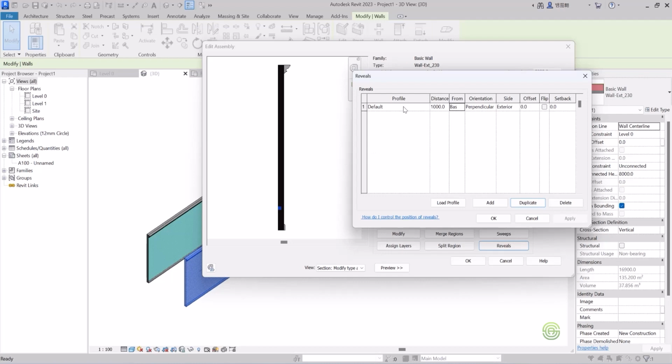It is scooping out the wall. Now in default, just change this to family 3 and now click apply. Now we can see we have a groove kind of thing applied on the wall. So like this, we can create multiple grooves at intermediate levels.